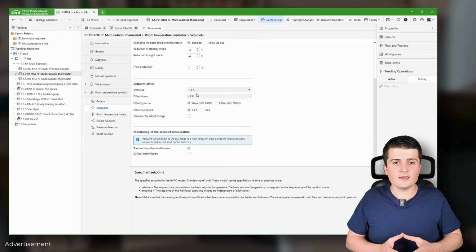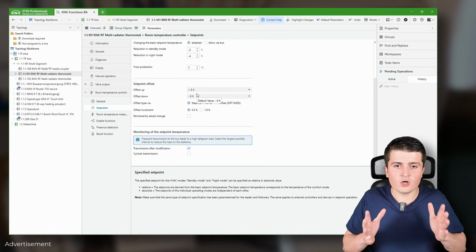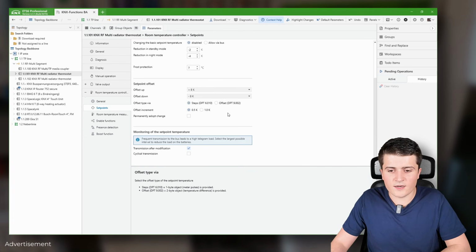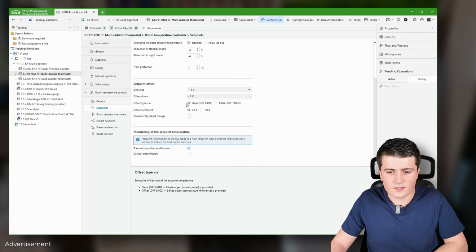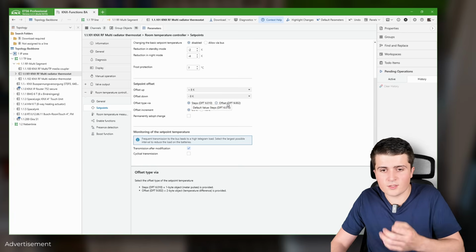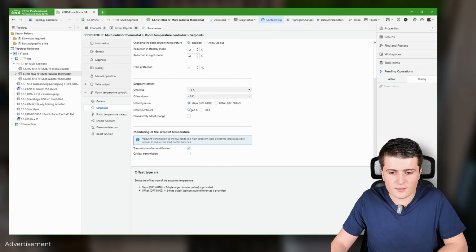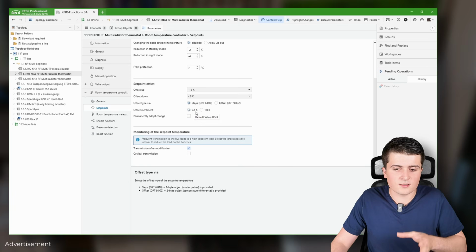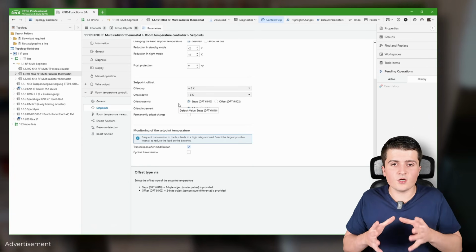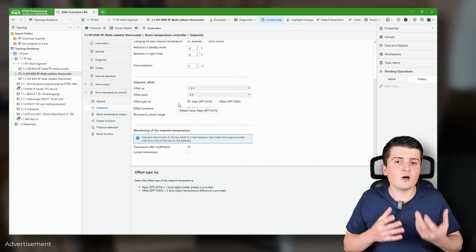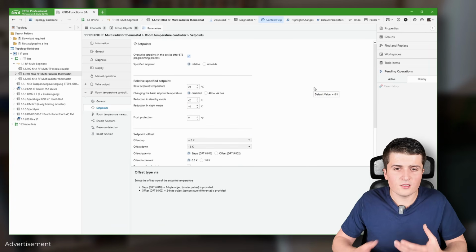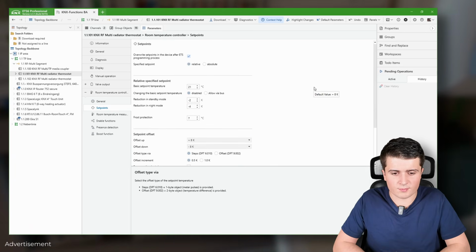Then down below here I can set the range within which the user can decide how many Kelvins he wants to have it warmer or cooler. Then I can define, is this set point offset a 1 byte or a 2 byte group object? Again, here you need to know which device you want to connect to it to set it to the correct one. And then I can set the increments. Is it 0.5 Kelvin or 1 Kelvin? The only thing that is missing here, in my opinion, is the option to have it as a 1-bit object. This is also something that is sometimes seen on other devices. But besides that, you are pretty free on what you want to set up here.